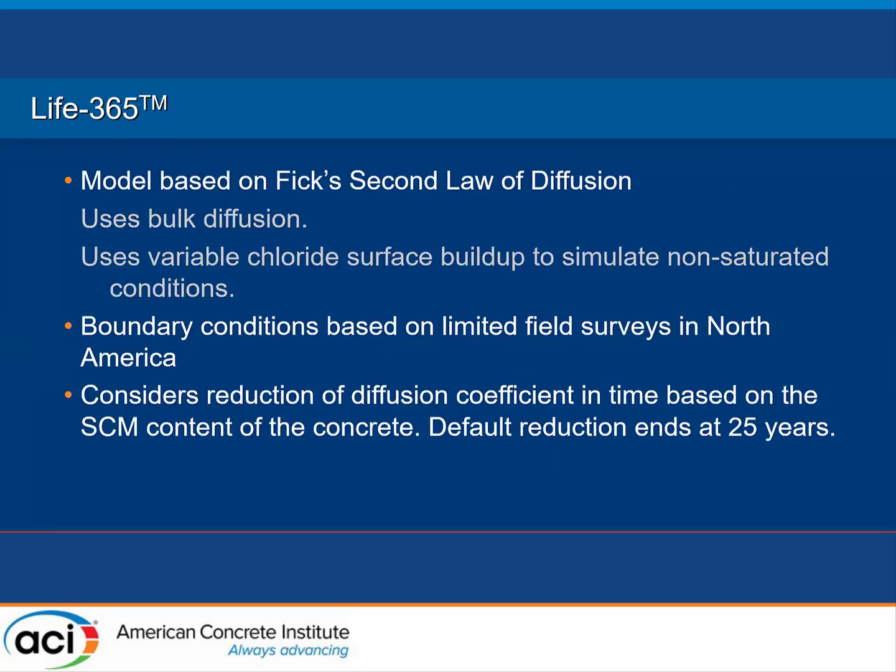Life 365 models based on Fick's second law of diffusion, uses bulk diffusion, uses variable chloride surface buildup to simulate non-saturated conditions. But boundary conditions are based on some limited field data in North America. I think, as just shown by Doug, some of the surface loadings on chlorides are a little bit on the high end. It considers reduction of diffusion coefficient with time based on the SCM content of the concrete, and it does that for a default up to 25 years.